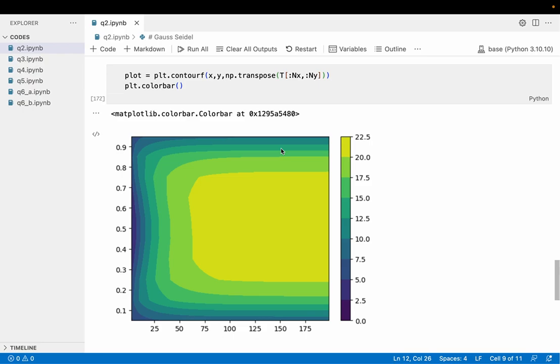The only point that I want to highlight here is the temperature. You can see we have non-dimensionalized the temperature, and the temperature should be between 0 and 1. That is what is happening on the boundaries. Here you have something close to 0, and on the top you have something close to 1, but in between is where you have temperatures that are much higher than both of these boundaries. This is essentially because of your viscous dissipation, which is continuously adding energy and increasing your temperature in the interior region, in your core region.